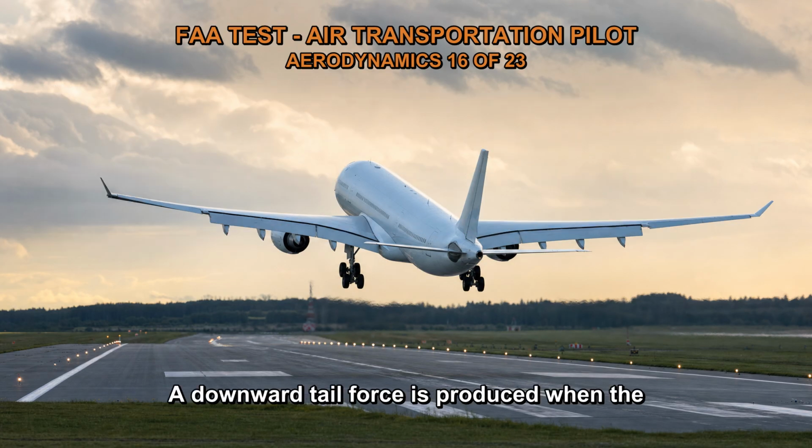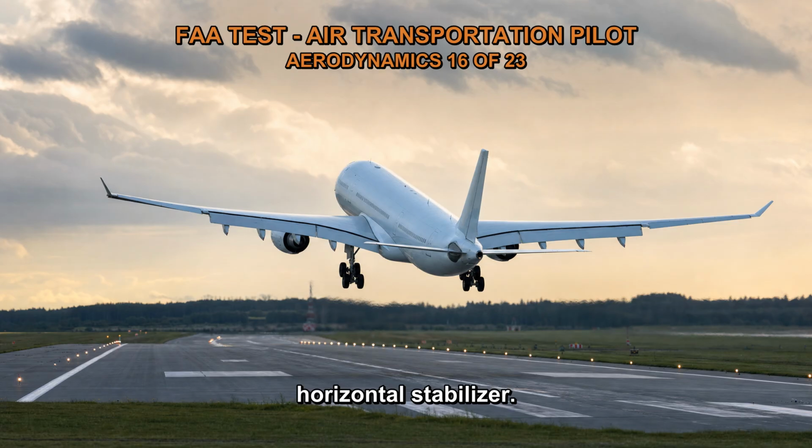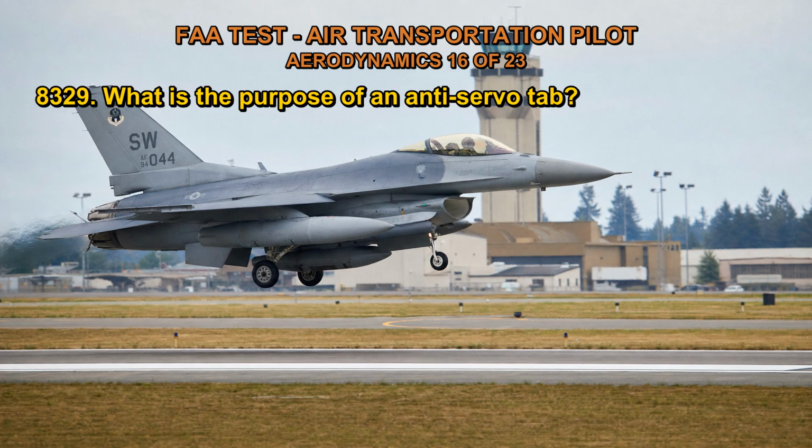A downward tail force is produced when the air flowing behind the trailing edge of the wing collides with the upper surface of the horizontal stabilizer. The pilot can trim the control forces to 0 and the hinge moment to 0 for a certain flight state by using the trim tab.